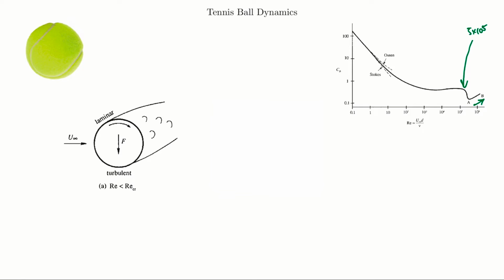Okay, so let's first look at this sort of weird case of the negative Magnus effect, which frankly doesn't come into play that much because most of these balls move at a Reynolds number above the Reynolds critical point, and they're usually pretty rough, right? But anyways, let's look at the negative effect first in figure A here on the left.